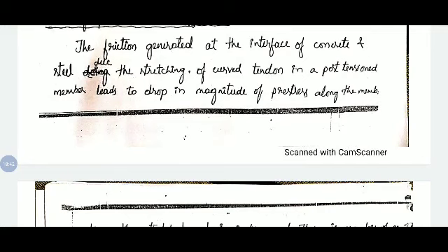if it is straight, no issues. But if you are providing curved tendons, obviously the tendon will come in contact with the concrete surface of the duct. So in that case, when you apply the stresses, if you are applying stress of 500 kilonewton at one end, it may not be 100% acting on the tendons because of the friction.